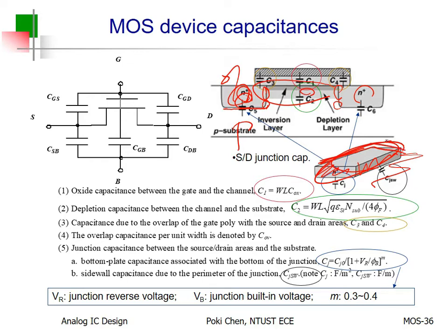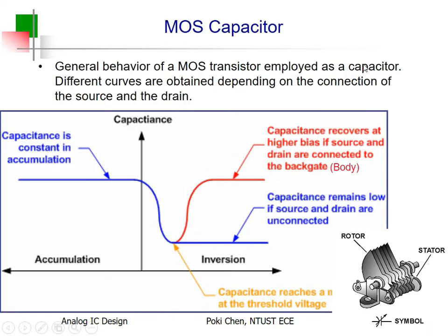3 side walls and 1 bottom plate dominate. And the inner one, I mean connected with channel, has very few parasitics. Got it? So, if you would like to speed up the operation of the MOSFET, you had better reduce the parasitics for all those 3 side walls and the bottom plate. But how? By stack layout. 把它叠在一起. Later, I will show you.